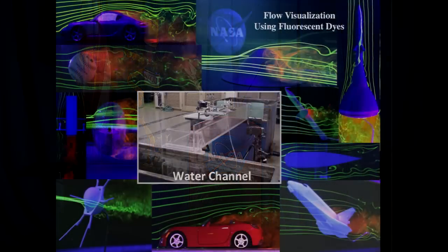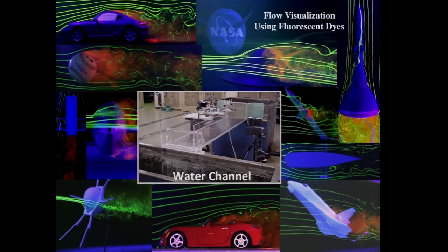So I talked a little bit about wind tunnels and how we use air to move over our models, but we could actually use any fluid. Here we have a facility called a water channel, so we're moving water across our model. So how does this work? Well, we have an upper channel and a lower channel, and the water moves from the upper channel through our test section back down to a lower channel. It gets pumped back behind here. That's not shown on the photo.